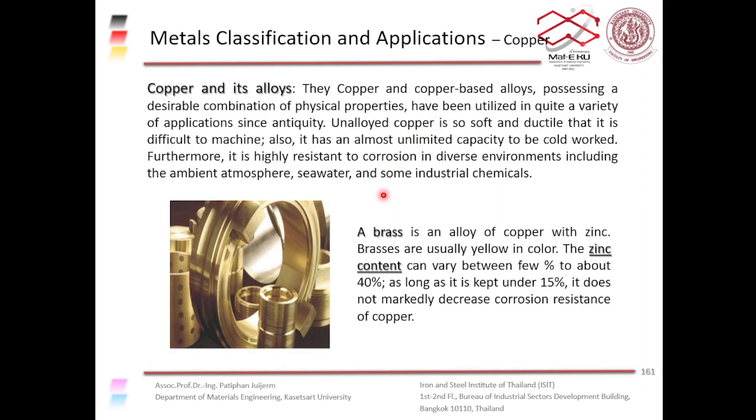Okay, copper is very resistant to corrosion, especially in seawater. So, for example, steel is very bad at withstanding seawater. It will corrode really quickly in seawater. Even stainless steel can be corroded in seawater. But copper alloys like brass are very good against seawater. You don't get any pitting corrosion in brass or bronze.